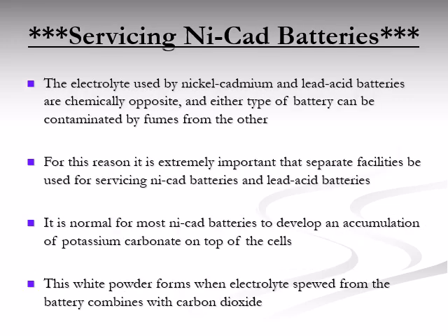During NiCad servicing, keep NiCad and lead-acid battery servicing areas separate. NiCads may develop potassium carbonate deposits.